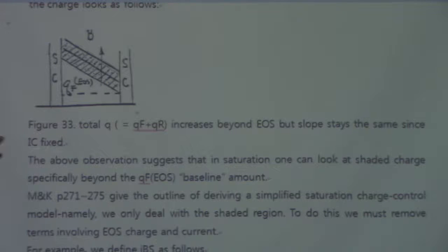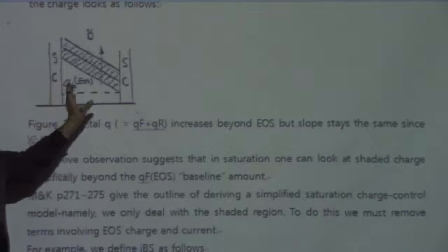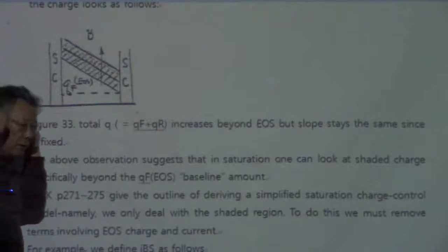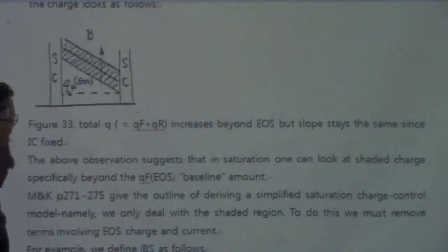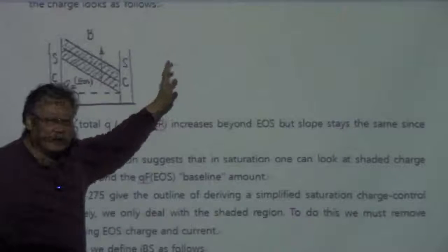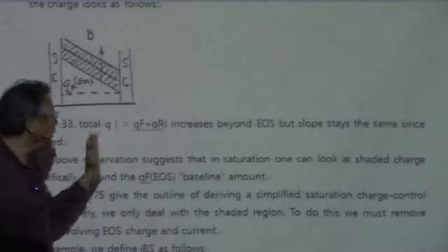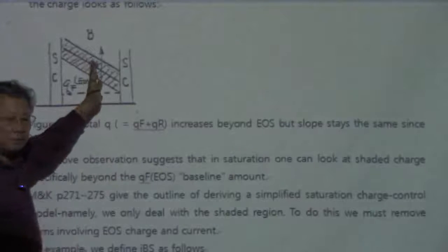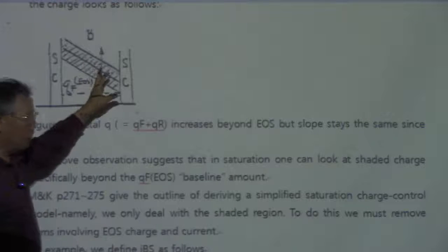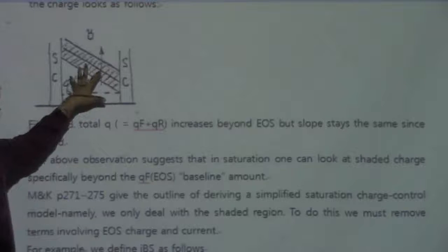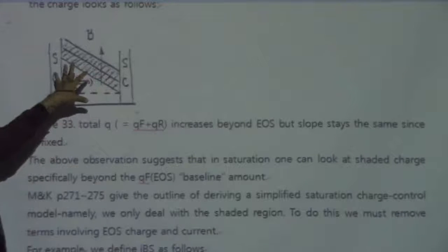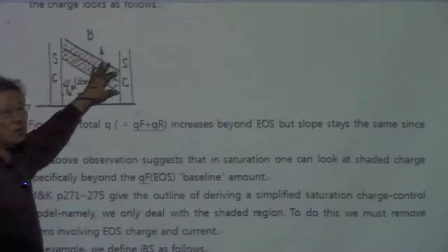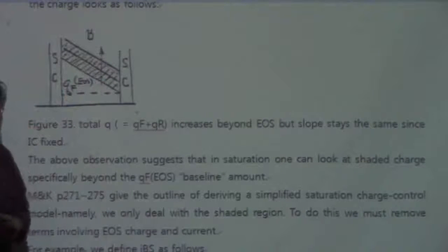But what happens if you want to use this device in a switching mode? If you put some input on this so that you have a steady state current as an output with the base input, now if you want to change it, then this device is not going to make a proper response to the input until this stored charge is eliminated.